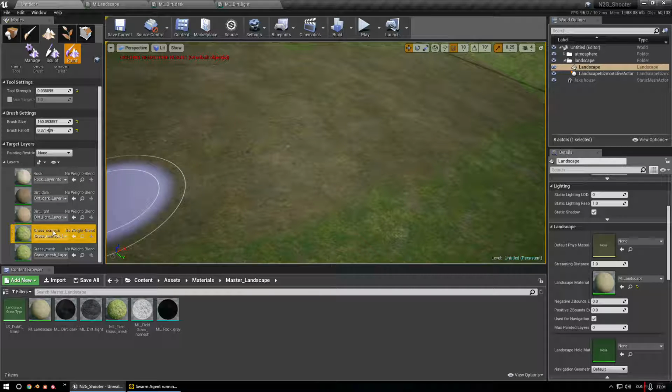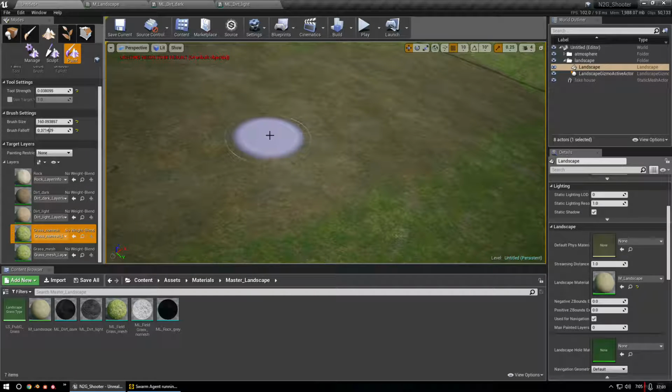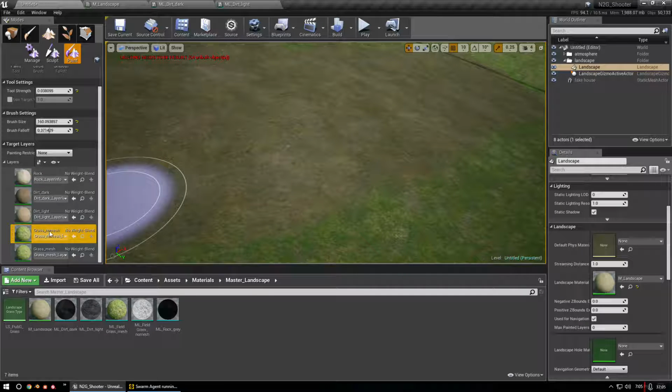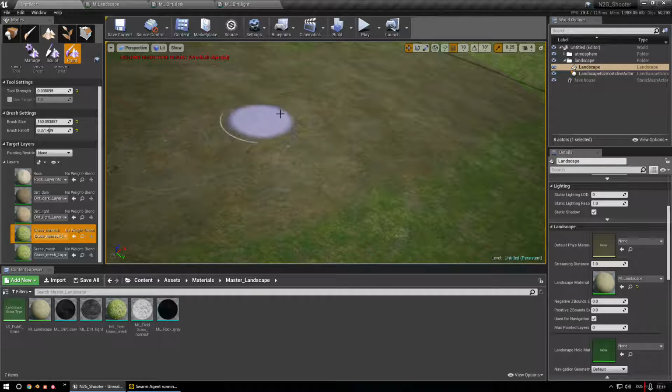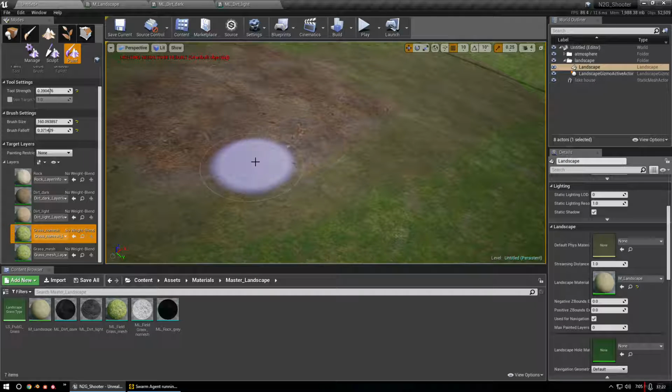What we're going to do here is hold shift and remove this mesh area from this no mesh grass underneath. We're going to remove it, and that dirt's going to pop. See how that dirt's actually pulling through now? I can pull this up a little bit bigger here, and we're actually just removing the grass from below the dirt, so it's not there anymore.